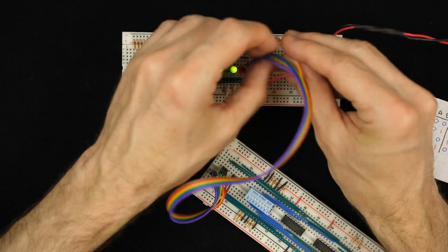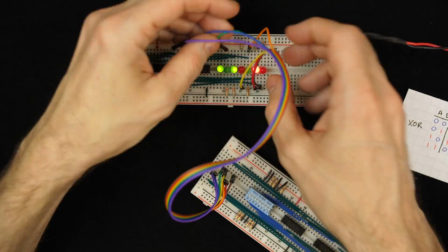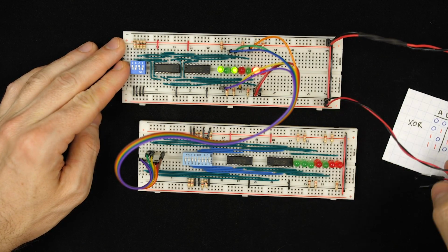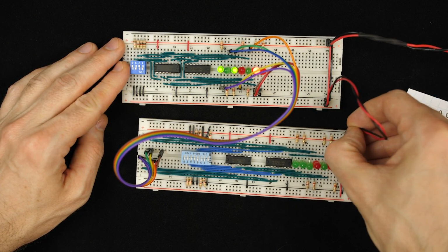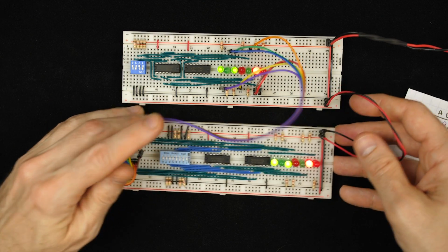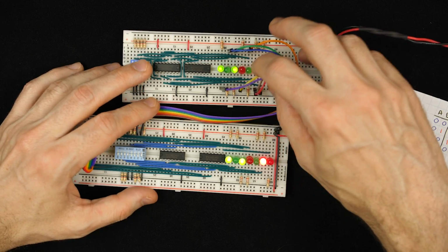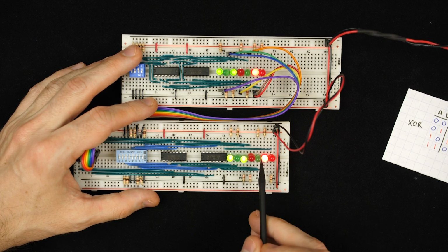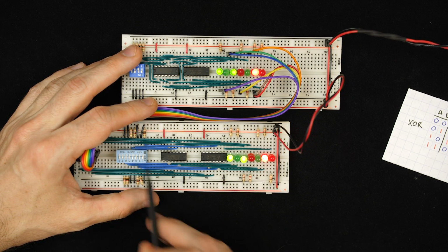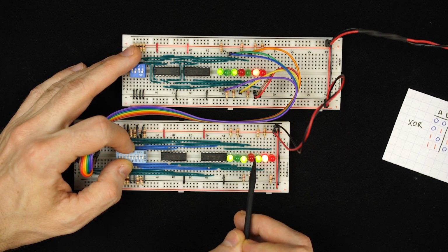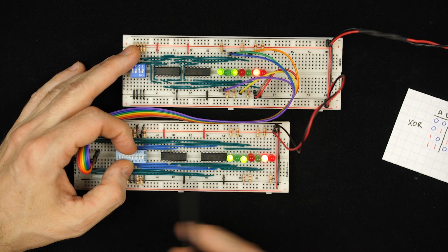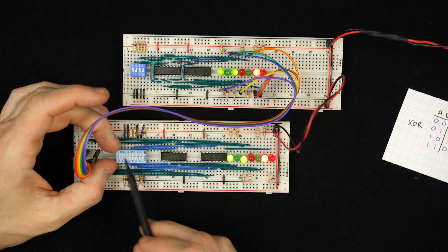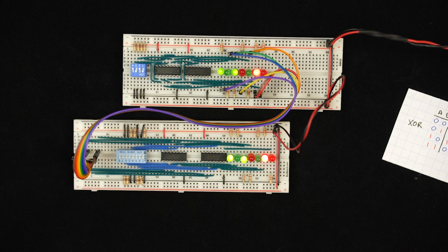So I'll hook up the 7 inputs of this to the outputs of the Hamming encoder that we just made. There we go. And then I'll also connect the power and ground through, except I'll hook it up the right way around. And there we go. So what we should see is this be the exact same. Whatever we've got here in the top, we should see here, except that I can flip a bit. So if I want to flip, let's say, this first data bit here, or bit 3, I just flip it and that'll turn it on. If I want to flip the second bit, I can flip it off just by flipping the switch here. So this circuit just lets me introduce whatever error I want so we can test out the error correction that we're about to build.